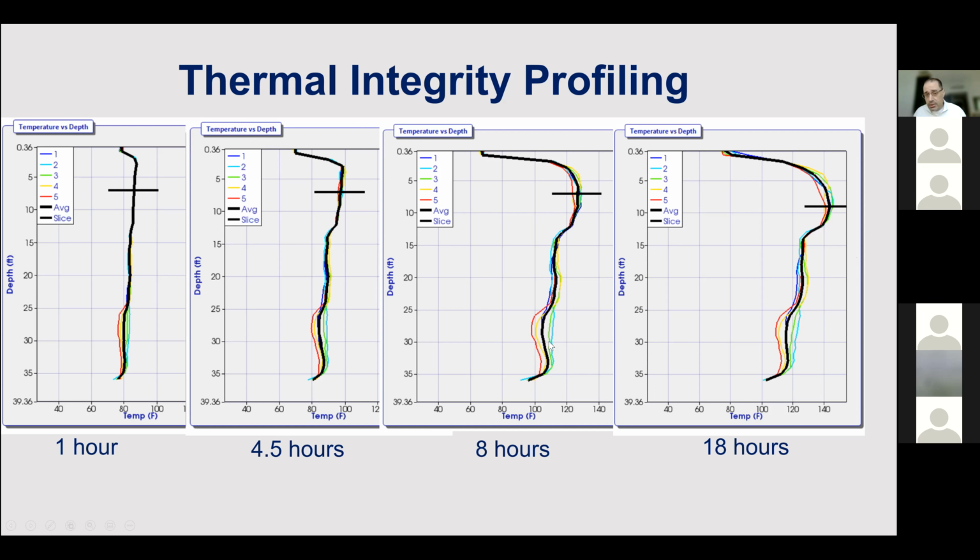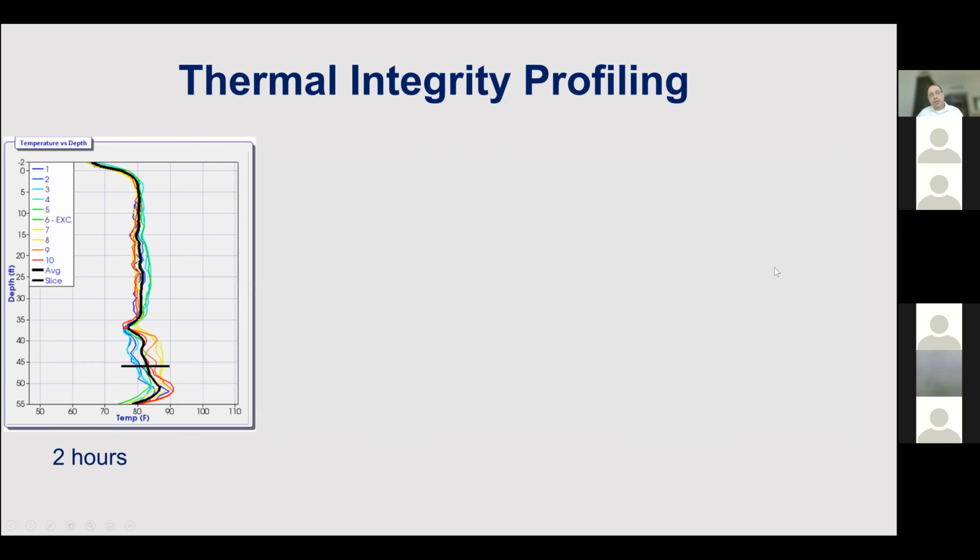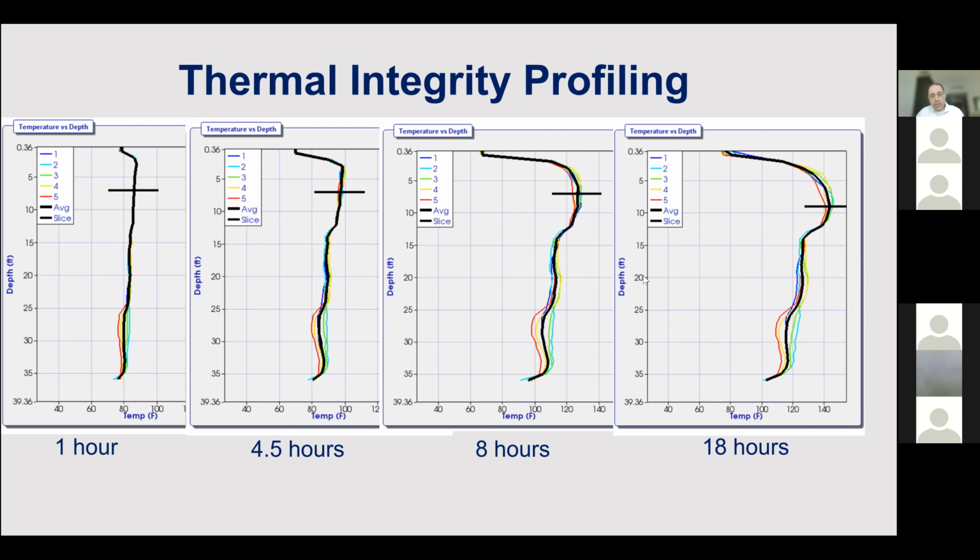In this case, it was a shaft embedded in a rock socket. So during the installation in the rock socket, there might have been some cage misalignment. But generally speaking, looking at this shaft, we expect to have a bulge because at the top there's maybe a bigger cross section. There's nothing showing a major defect, just a bit of cage misalignment. So quickly you can tell the contractor that this shaft is reasonably okay and you can move on.